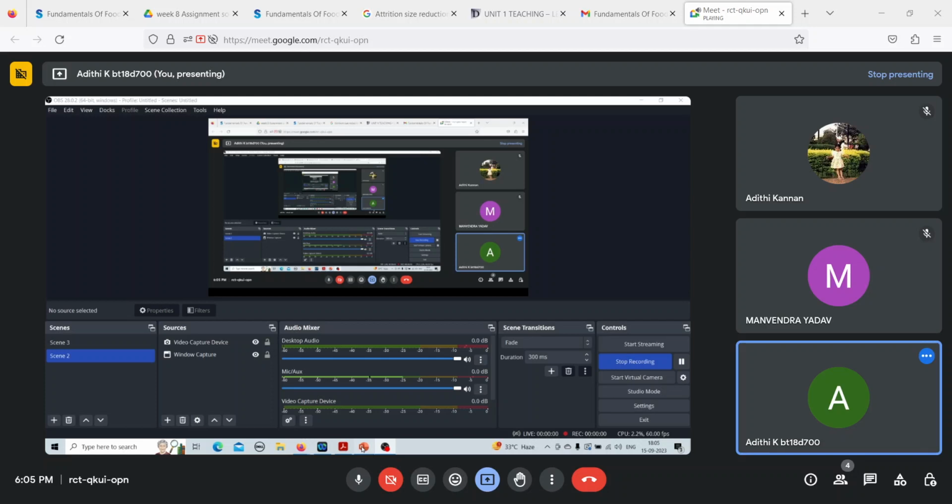No, if you remember, the hammer mill works by the force of impaction. So in order to understand it better, impaction is basically you have a substance that is coming forcefully on your food material. Like say you are hammering a food product. So hammer is involved in impaction. Attrition is that you have food products here and you have two forces acting in the opposite direction. Basically, like rubbing. If you have something between your palms and you keep rubbing it, that process is known as attrition. You have one force acting in this direction, one force acting in the other direction, and it is continuously rubbing the food material between these two forces. So this is known as attrition.